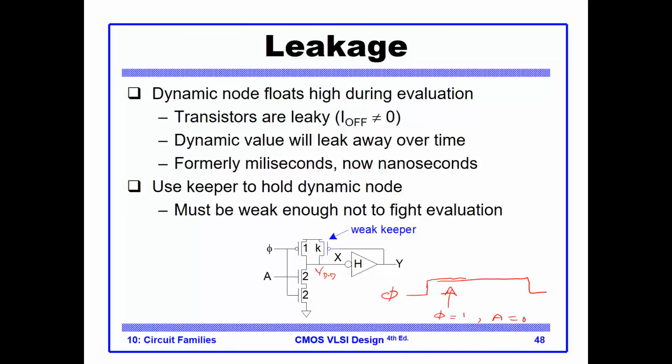Unfortunately, as we've studied earlier, even when the transistors are off, there is leakage current. And this leakage current will leak this value, and especially if this period is a very long time, it will leak all the way to 0, and that will cause an erroneous result.